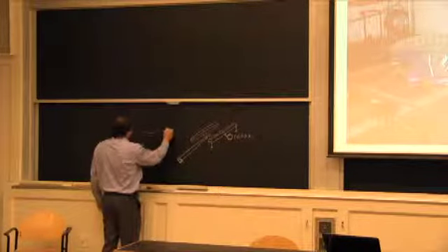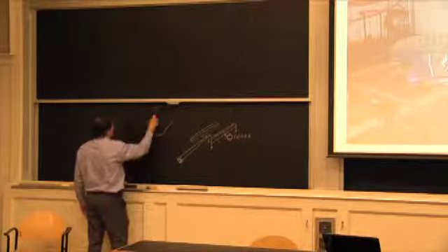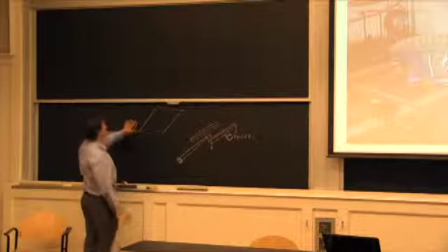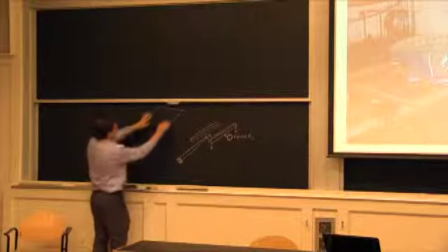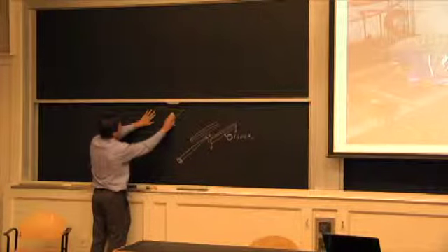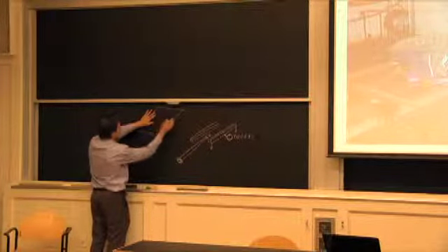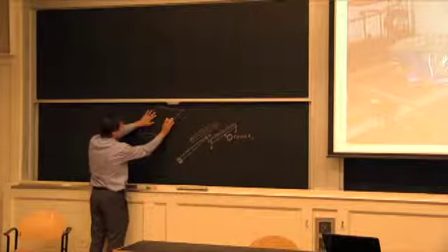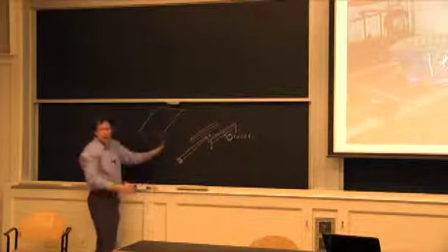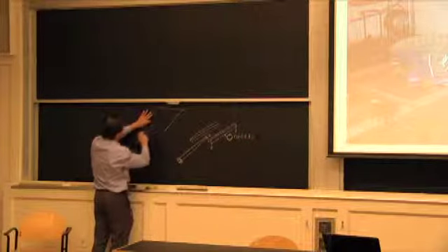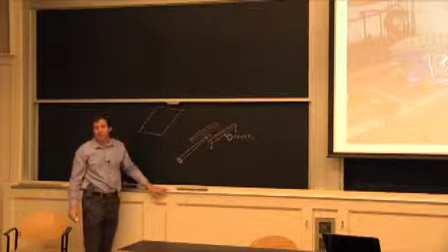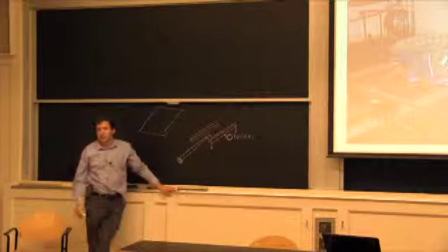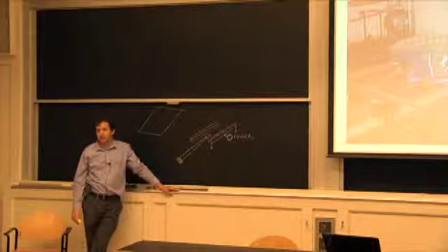So we start as a plane. It's 8 feet by 4 feet. So say the size of this board, a little bigger in this way. And instead of staying as a plane, if this wheel's pushing up very quickly, it will try to move up here, and this one wants to stay this way. And the only way you're going to prevent this deformation of your floor is by the resistance of the connections at the corner in tension or bending. Basically, it's twisting as the bed. Yeah. Okay. But it's called racking, right?